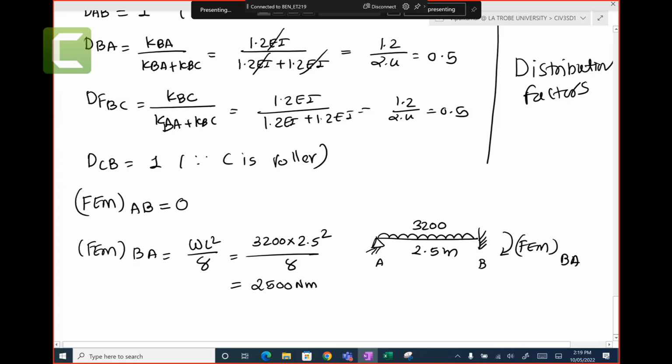We have a table. Look at the table. In that tables, you can find it. B is internal supports fixed. We don't touch the end supports. Okay, so we find the fixed end moments. And you know why we find the fixed end moments, right? Because displacement method does not like the load coming onto these members. It likes when those loads are moments at the joints, and then we distribute those moments. Right. After this, we build the tables.